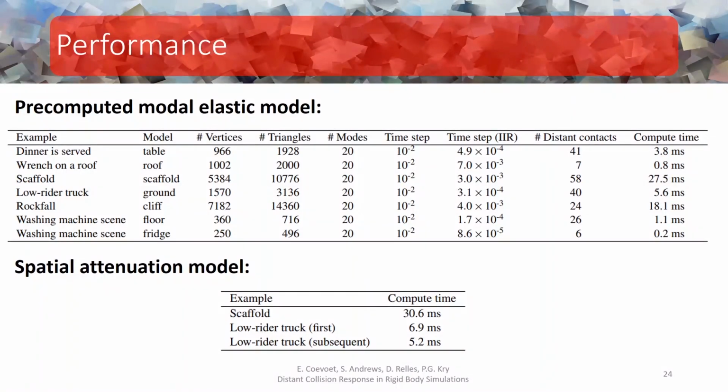Finally, we demonstrate that our approach runs at interactive or real-time frame rates by reporting performance details for our implementation. The compute time using the reduced elastic model increases with the complexity of the FEM mesh and number of distant contacts. However, we observed that determining the barycentric weights tends to dominate the overhead, and we believe an optimized or parallelized implementation of this function could significantly reduce the compute time.